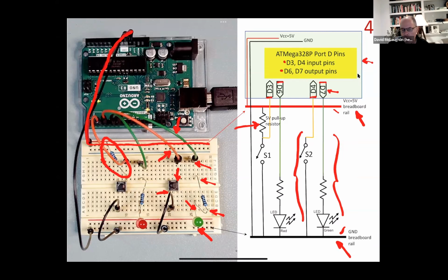An upshot of this whole thing is you don't need an external pull-up resistor, because you have internal pull-up resistors inside the Arduino Uno ports, provided you activate them. If you don't have pull-up resistors, internal or external, you'll end up with floating inputs. They'll have undetermined values, and the system will behave erroneously.